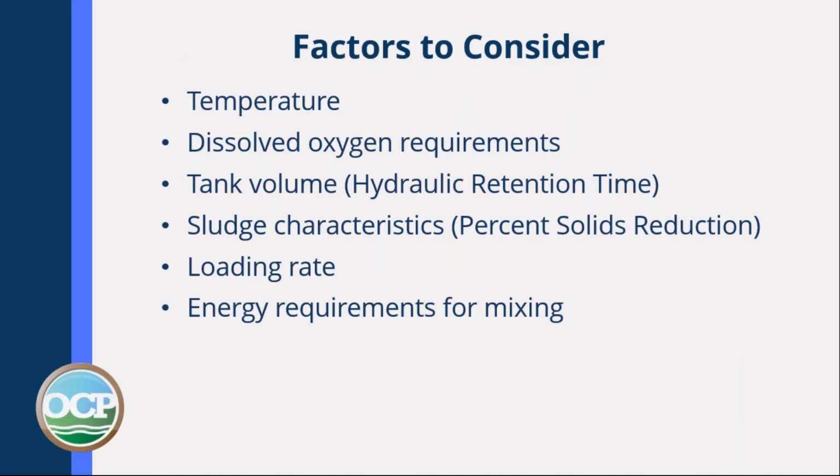Factors to consider for aerobic digestion are everything we always teach. We say temperature is a factor. Digestion will go faster as the sludge temperature is warmer. Your dissolved oxygen requirements: you still need oxygen going to your tank for the sludge to digest properly.